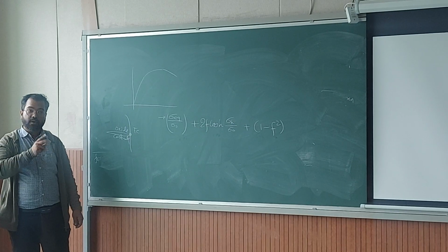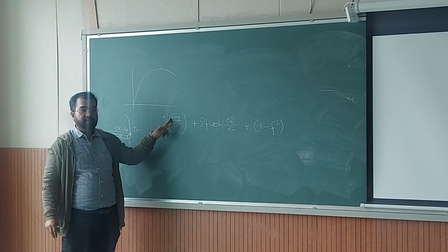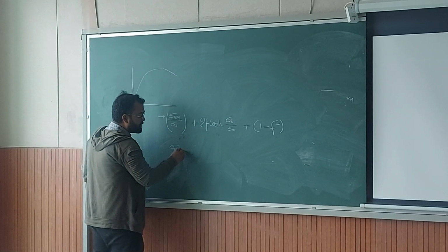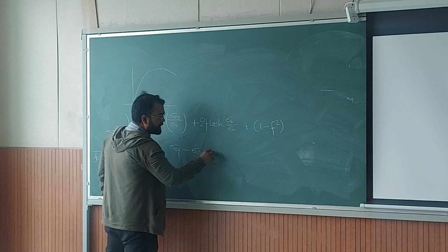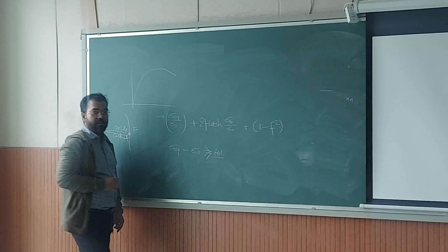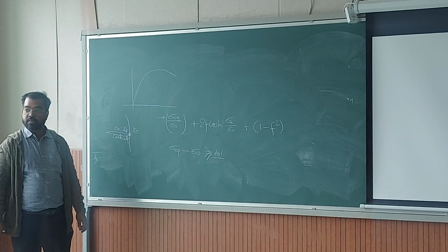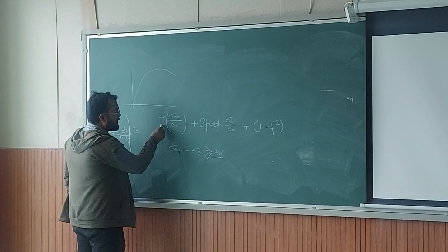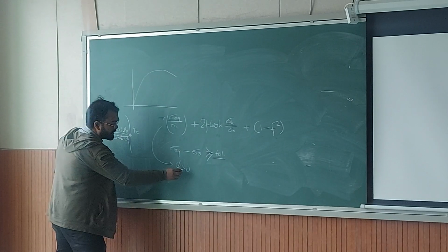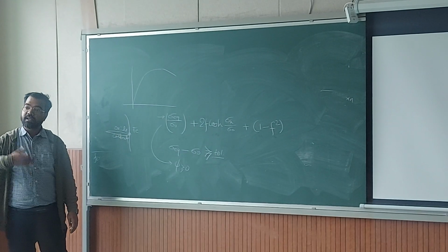Okay? So in this case also we are calculating von Mises, but we are not saying that when sigma equivalent minus sigma naught is greater than or equal to tolerance, we go in the plastic domain. We are not saying that. We are saying that this must be greater than or equal to 0. Then plasticity will happen.